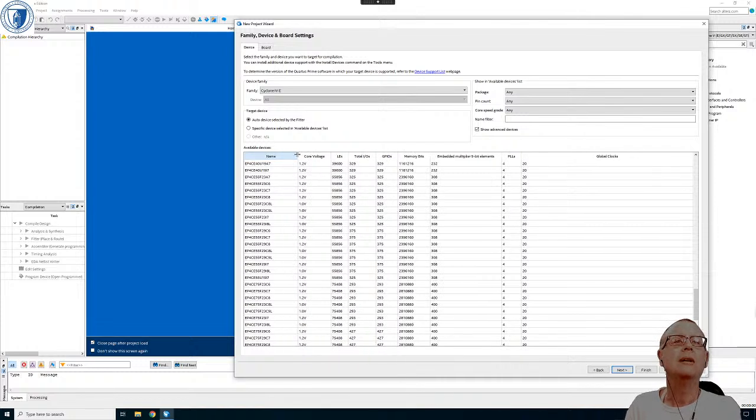One reason, even if you don't normally have to run Quartus as admin, if you're running it to program the device, so to get access to the USB connection, you may need to just for that. There may be other reasons before you actually get to run it, even just compiling. But yes, sometimes you have to run it as admin.